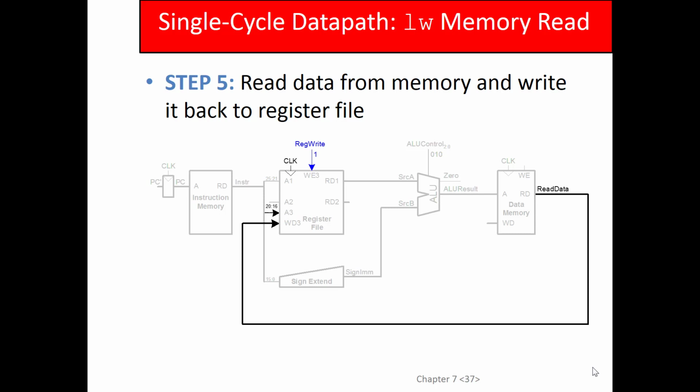In my class, they used to not rely on block diagrams. They used to use register transfer language to show what's going on here, right? This is an alternative form. You can define what's going on here using a programming language called register transfer language, which is kind of like pseudocode for hardware, except it's at the data path abstraction. So these are all data paths, right? So the idea is that what's really happening is I could think of it this way.